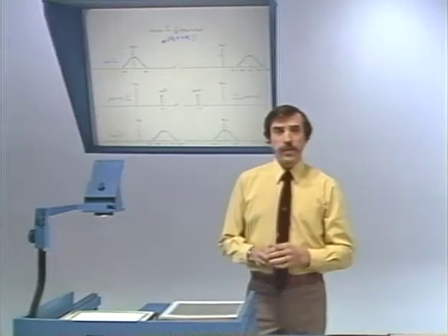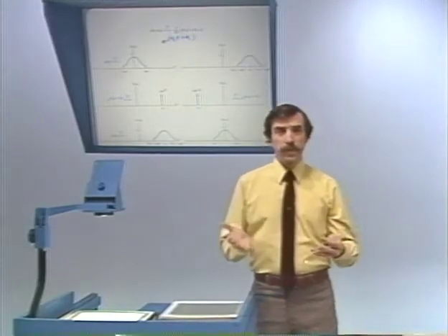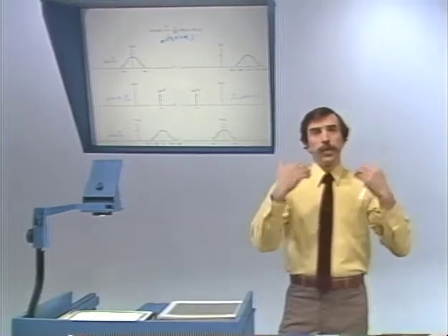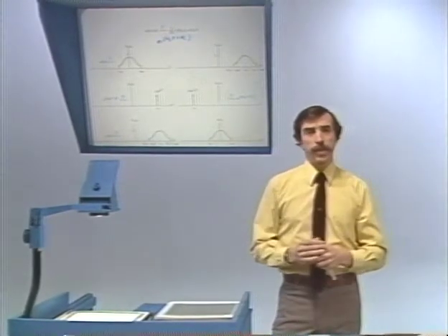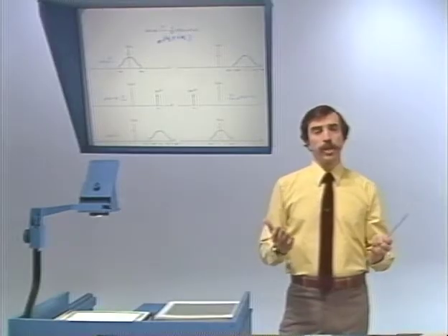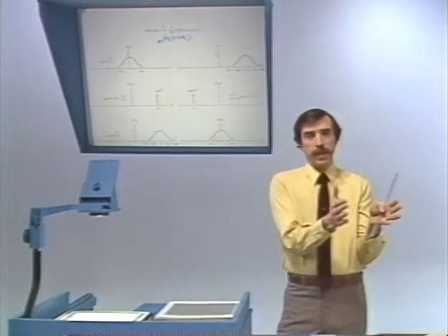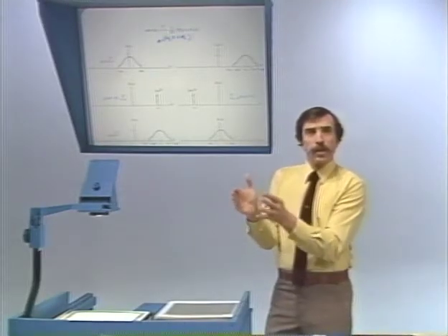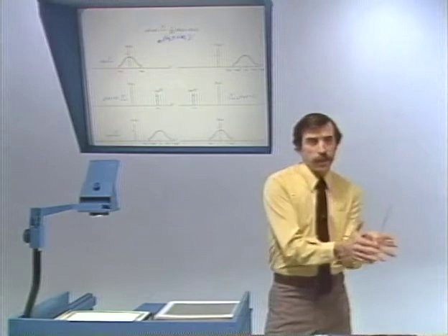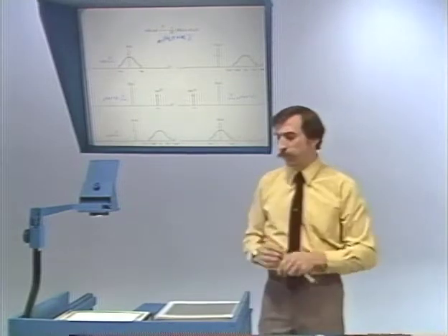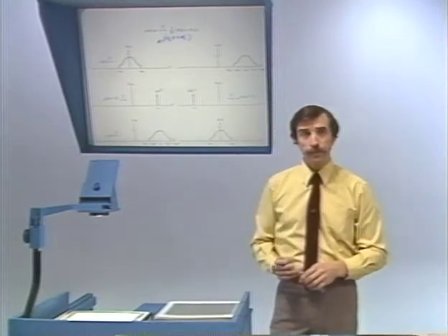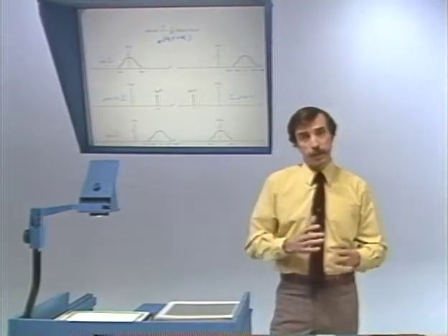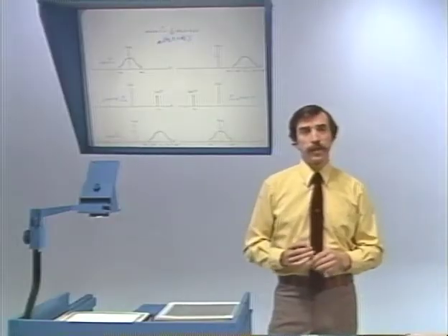So what this says is that if we have a signal, x of t, and we use it to modulate a complex exponential carrier, in the frequency domain, what we've simply done is to take the original spectrum and shift it in frequency so that what was originally at 0 frequency is now centered around the carrier frequency. Now, we've modulated, in effect, to a higher frequency. Things are happening in a higher frequency band.